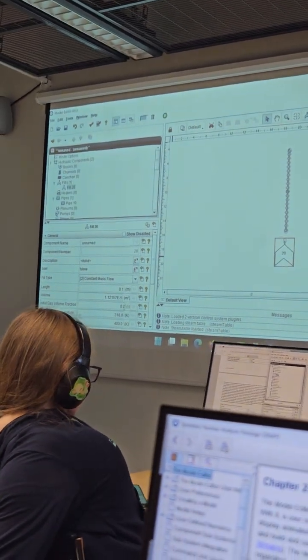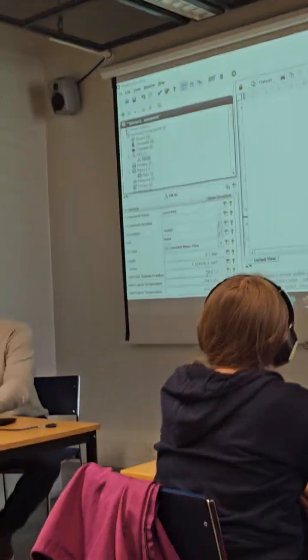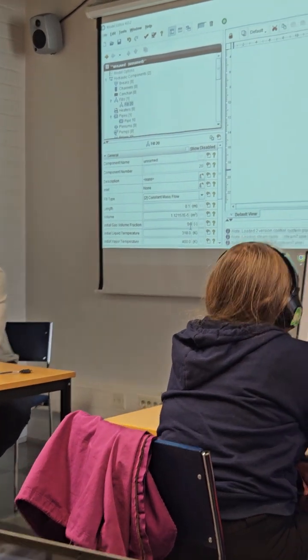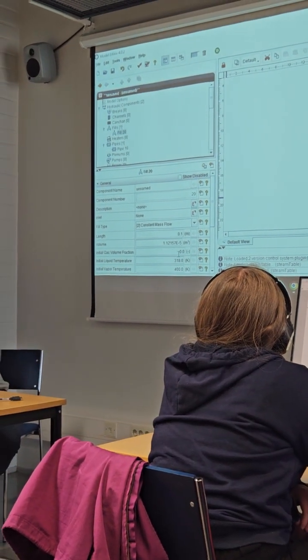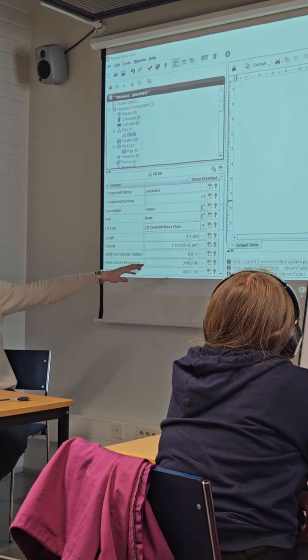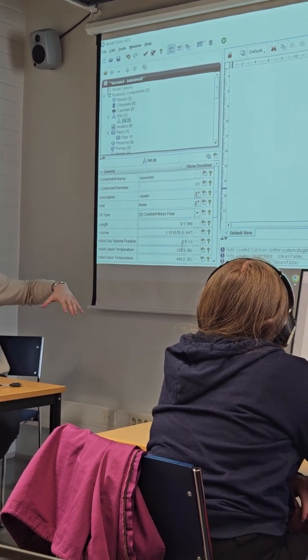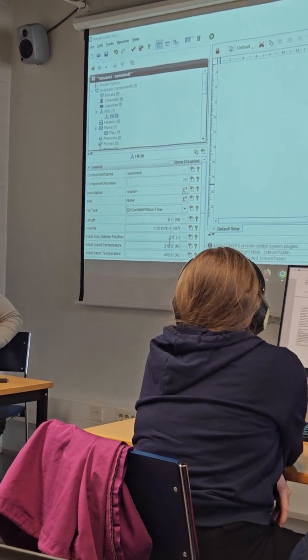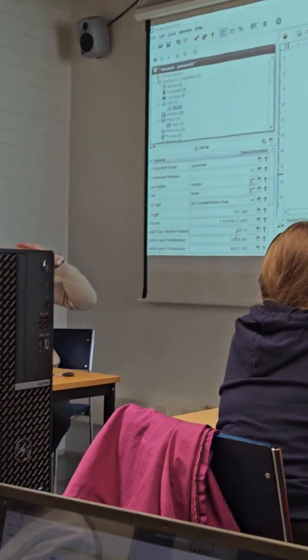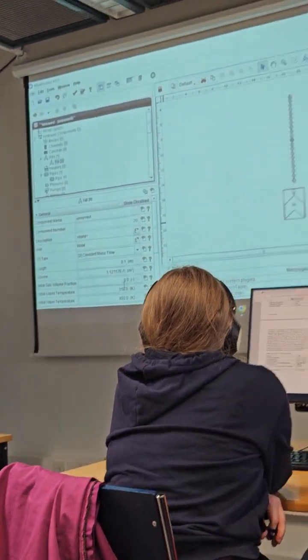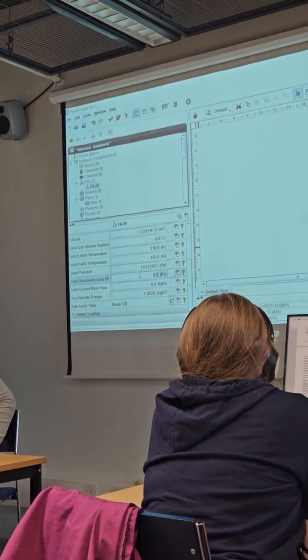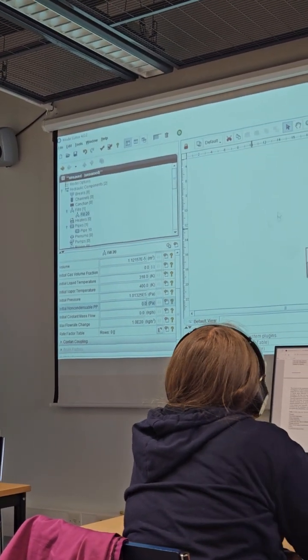Initial gas volume fraction is equal to 0. It is filled by water. Just to avoid the delay, if you define it as one first inlet, since the fuel component has its own volume, it will fill the fuel component and then just the pipe. You're right. So then we can leave it as 0.